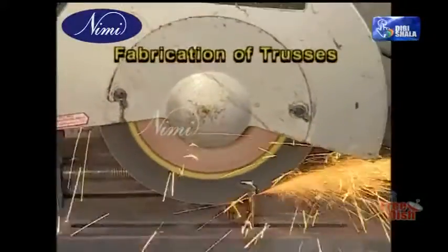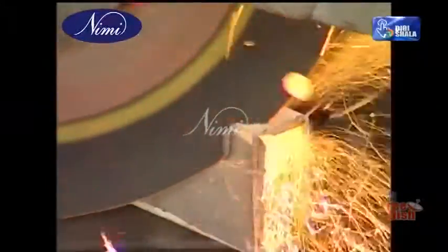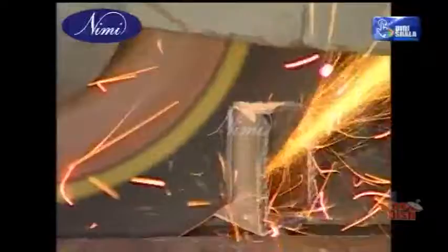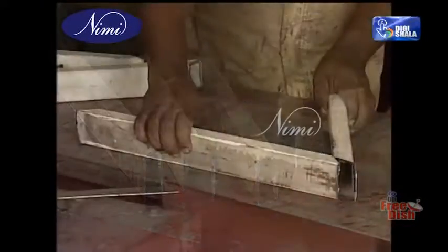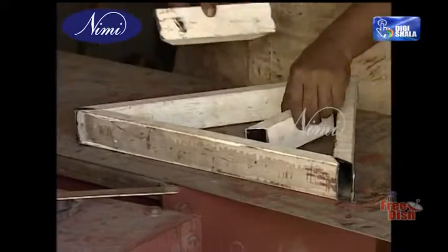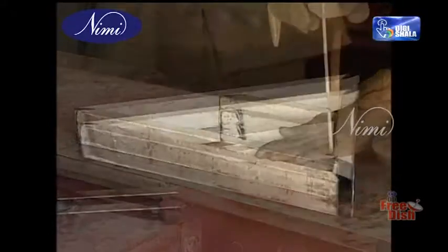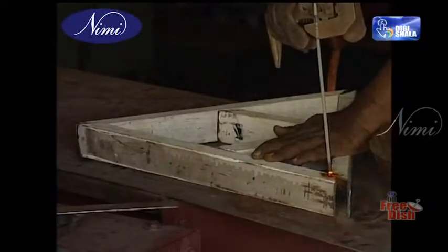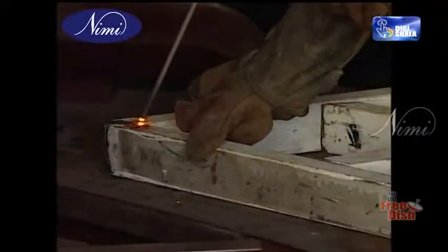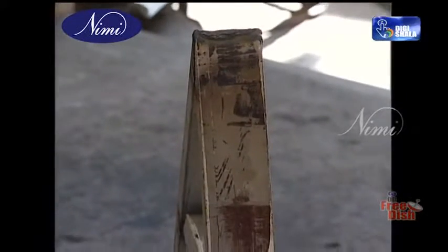Fabrication of trusses. Cutting the workpiece as per dimension as shown. Welding the metal piece by using arc welding. Inspect the trusses as per dimension as shown.